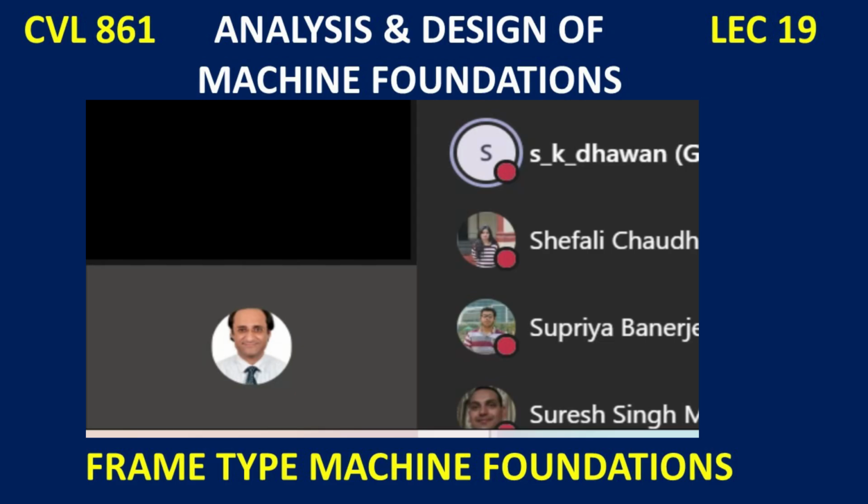We have to see that the results we are getting are within the range of 5 to 10%. The manual check matters because software is also made by a human being. And finally, as a young engineer, I would say that for any job you do in any office, the documentation part is very important. Here in IIT, so many buildings have come up where we probably don't know who did the structural designs, or what the design basis report is. There is absolutely no documentation.